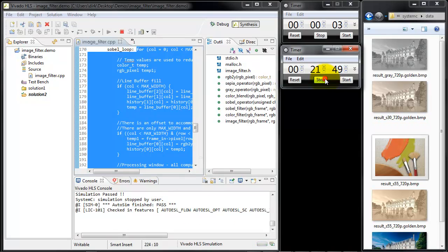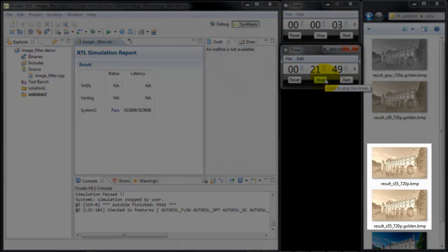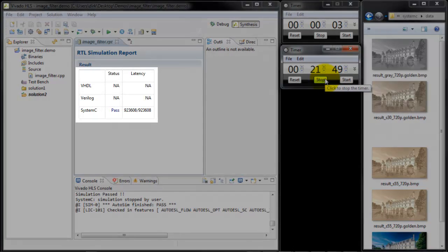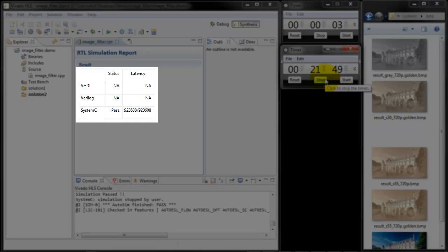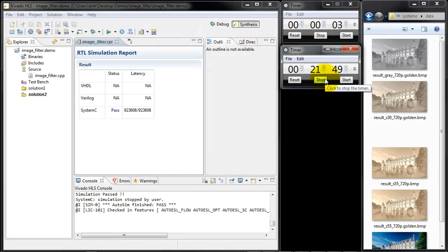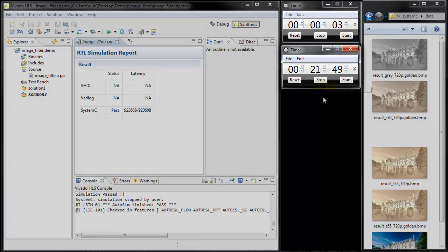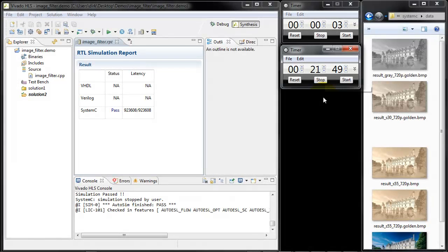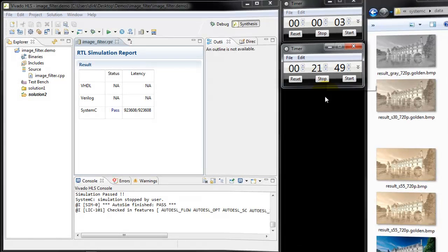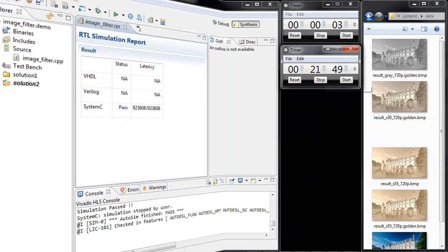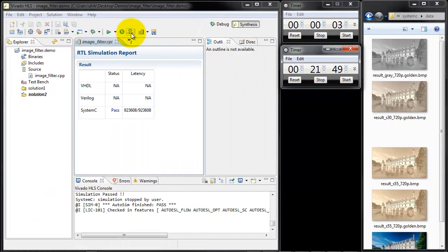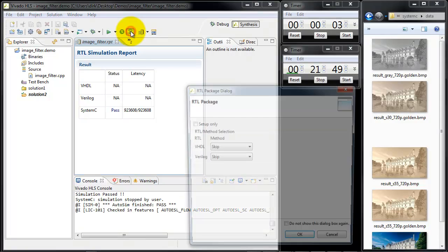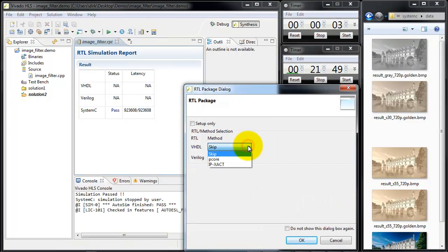We can see that the RTL architecture created the correct result with the image produced in our simulation directory. Vivado HLS also measures the actual latency and reports the success of the RTL verification. Note the huge gap in time required for C-based simulation versus RTL-based simulation. For larger designs or test benches, RTL-based fine-tuning simply takes too long. We have an architecture that satisfies our physical constraints and is functionally correct. All that is left is to pass it on to the system integration environment.